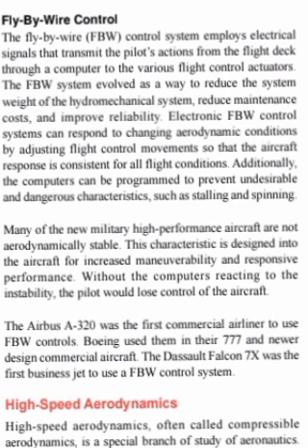Electronic fly-by-wire control systems can respond to changing aerodynamic conditions by adjusting flight control movements so that the aircraft response is consistent for all flight conditions. Additionally, the computers can be programmed to prevent undesirable and dangerous characteristics, such as stalling and spinning.